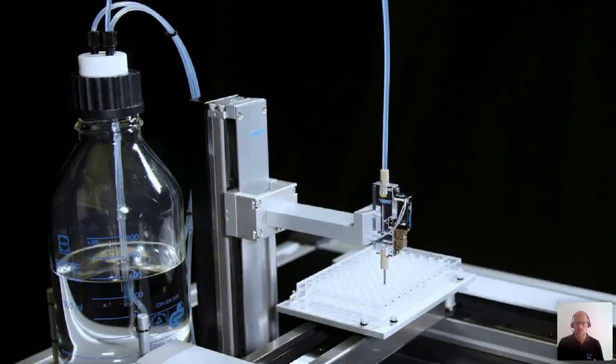And this is how it looks like with a little picture. You can imagine it. We have this bottle with the fittings. We put some pressure inside, and then we are going through a tubing to a manifold. On the manifold, we can find a metered separated valve, and then with switching on and off, going through channels, through this liquid fitting, through a needle, and then we will dispense. So very simple.